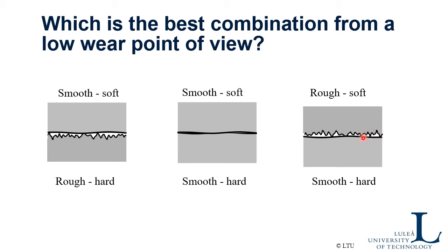On the other hand, there is a roughness on the soft one, so you create not too big areas of contact here. So the adhesive component will also be minimized. So this is a kind of tribological design you can think about if you aim at finding a wear resistant case and also a pretty low friction.